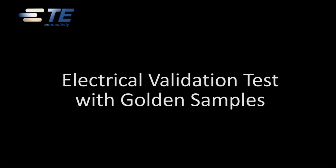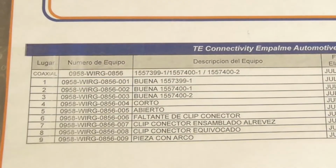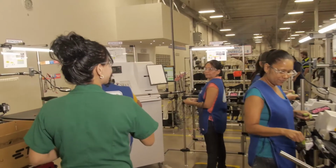Processing golden samples on the electrical tester. Golden samples are special parts that have known defects. The golden samples are used to assure the electrical tester can detect bad parts and are repeatable.